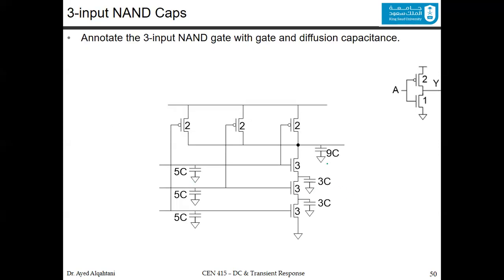Can you add up these capacitances together? Were they parallel like the inverter example, where we add them up together and that's it? No. Each capacitance is not directly connected to the other capacitances. There is always a transistor between them. Or this capacitance here is actually connected to the gate, and there is no current flowing through the gate. So we need to deal with these capacitors.